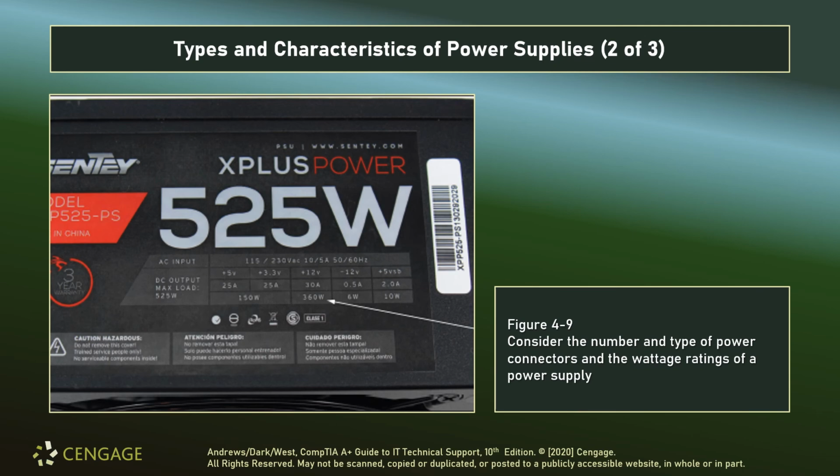So if we want to explain what these wattage ratings mean and how to identify them, usually we need to use these different label metrics, if you will. So let's take a look at what we have here. This is from Sente.com. If we take a look at the AC input at the top, it says 115 over 230, 10 over 5 amps, 50 or 60 hertz. So these are the operational parameters that it can use.